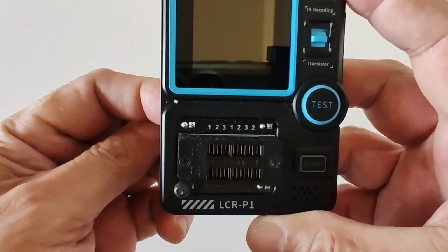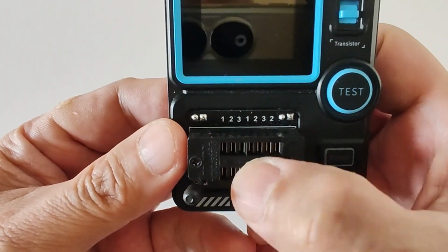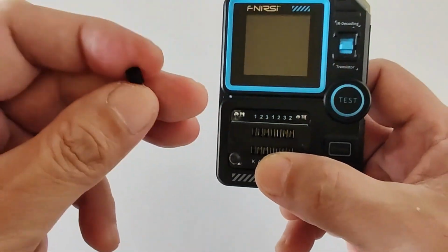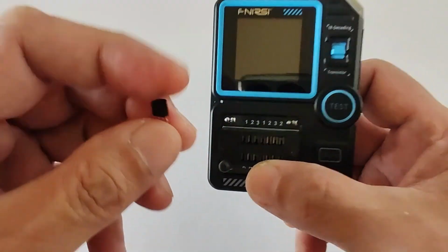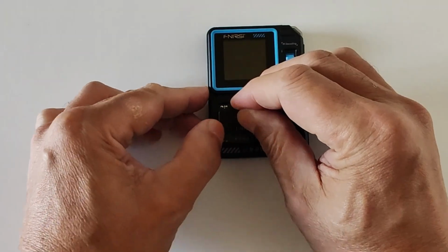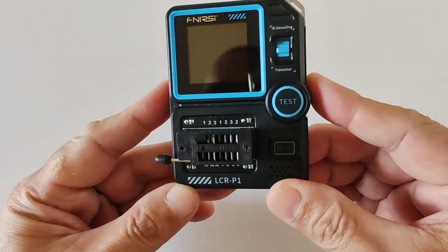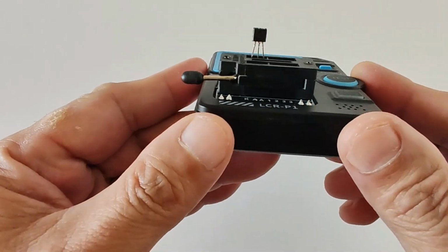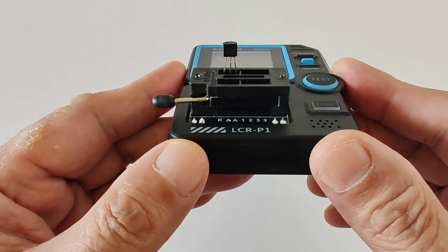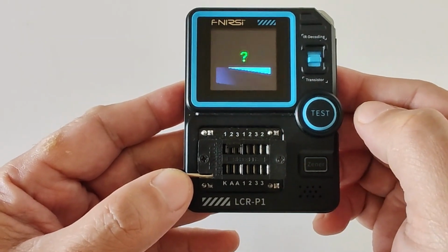Let's connect it here. I'm going to connect the transistor here. You see the numbers there, 1, 2, and 3 on this side of the top, with the flat face facing towards us. See the flat face facing us? Pin 1, 2, 3. So what does that mean? Pin 1 would be the one on the left, pin 2 would be the middle pin, and pin 3 would be the one on the right. Let's verify the pin configuration first.